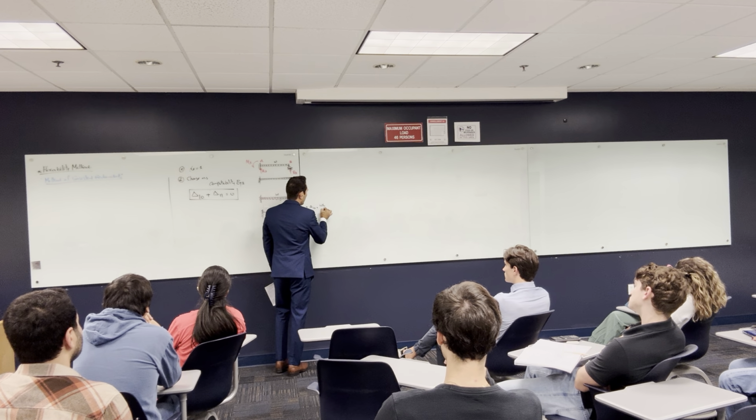That is the compatibility equation. And my mission is to find the value of F. If I found F, that means that I solved the problem, because that's the reaction that I want to find. So this is the method of consistent redundant, is to solve this equation. And the final bending moment or the final reaction is going to be that way.